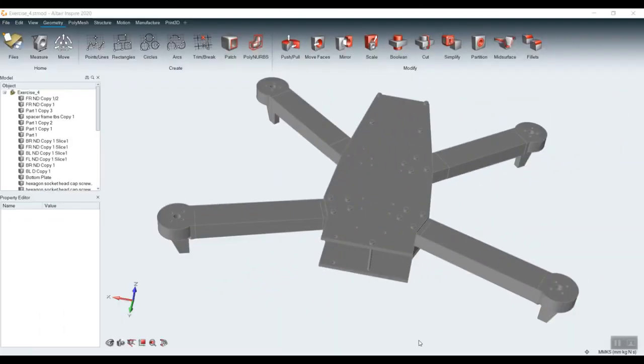In this video, we're going to cover connections within Inspire. Up till now, we've been utilizing models that are just a single part, but many of the types of parts that we're going to want to be doing analysis and optimization on are going to consist of multiple parts, potentially large assemblies, and we want to make sure that we're accurately modeling the interaction between all of the different parts